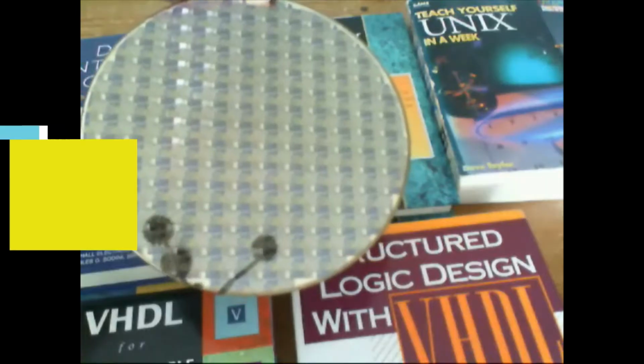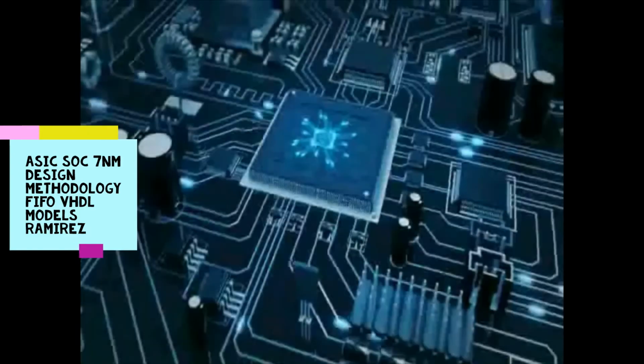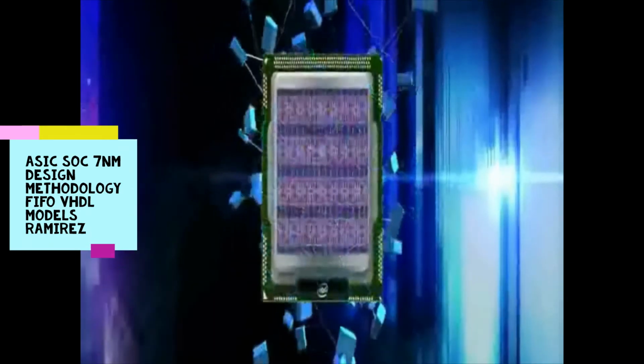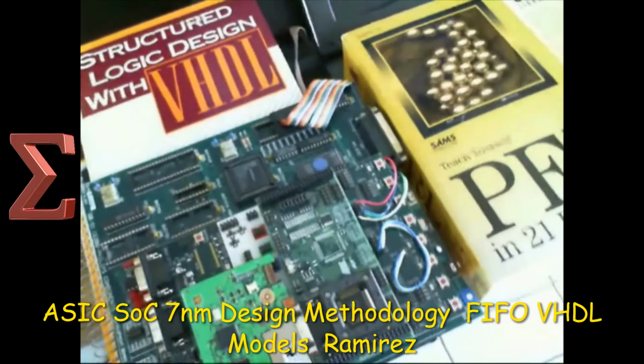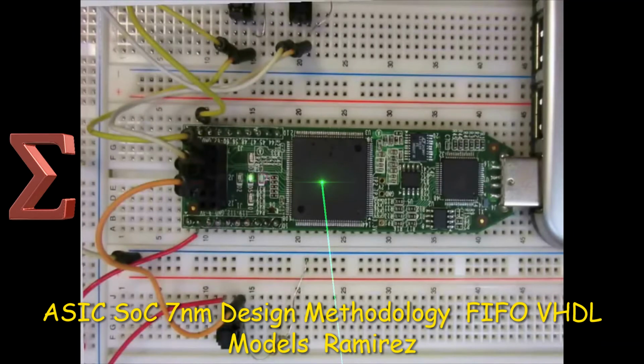It also allows VHDL architecture selection, and it also replaces the HDL arithmetic operators in the code with the DesignWare components. And finally, it automatically executes the link command, which resolves all the design differences.